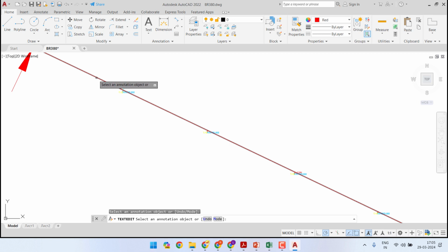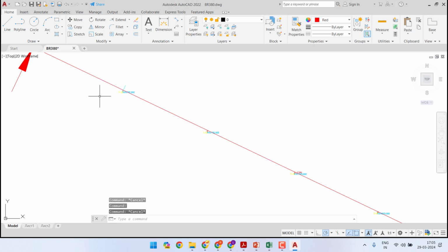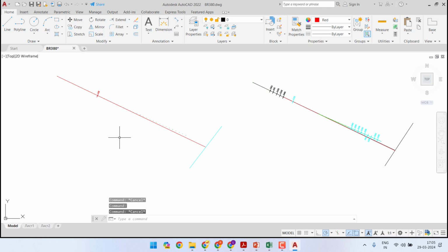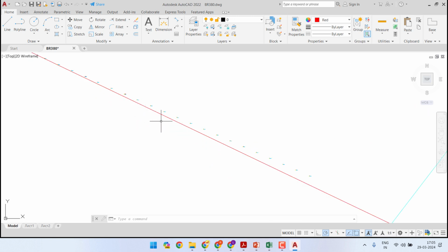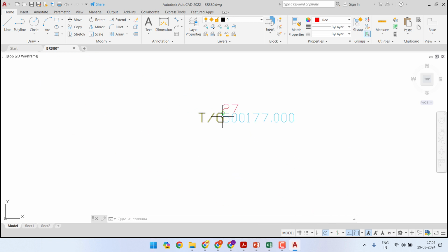We already know the first terminal tangent. Now for the purpose of our analysis, what should be the ideal second tangent, where should it be? There are many options for that. The first option that should come to our mind is let us take the farthest point that we have, that is station number 27.